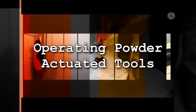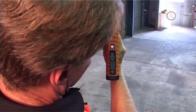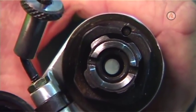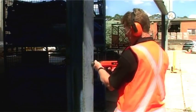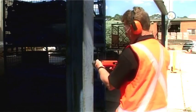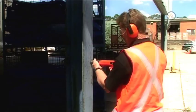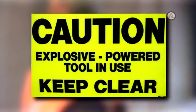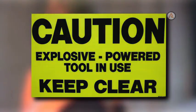Operating powder-actuated tools. Before operating a powder-actuated fastening tool, check that the tool does not contain any live power loads or fasteners. It should be tested to ensure that it is functioning correctly. Press the tool against the work surface and pull the trigger. Listen for the click of the firing pin dropping. Repeat this test a number of times to check consistency. Prior to and during firing of the tool, an approved warning sign should be displayed at or near all entrances to the place the tool is being used.